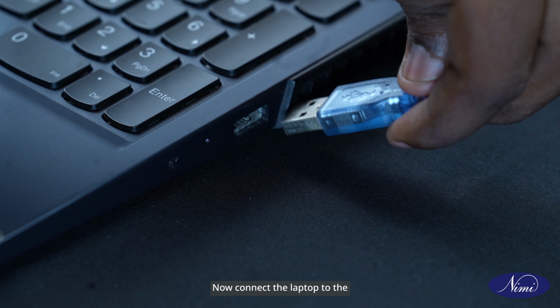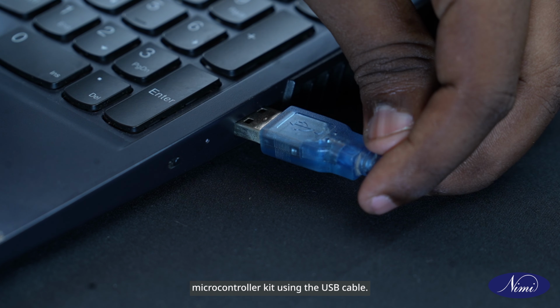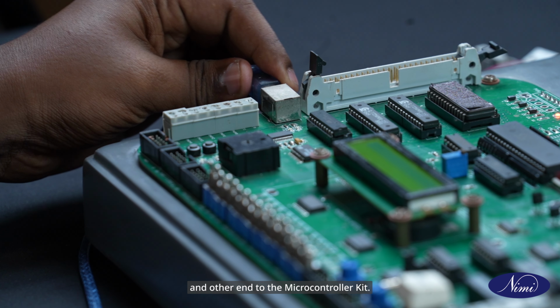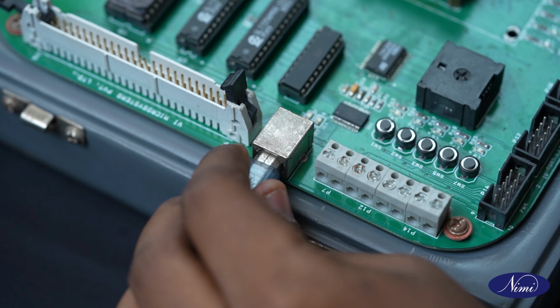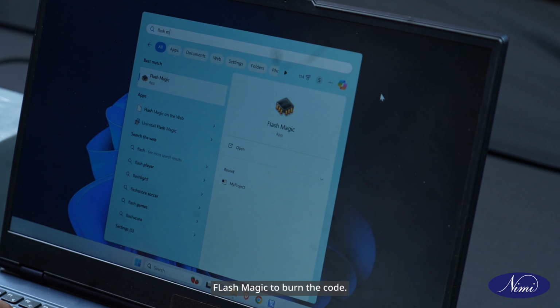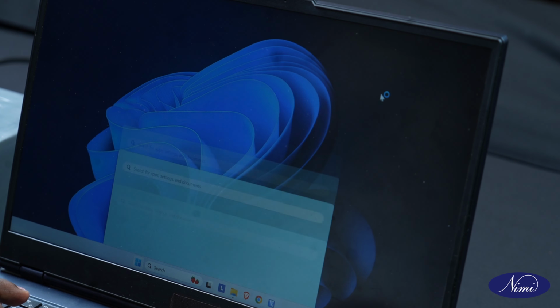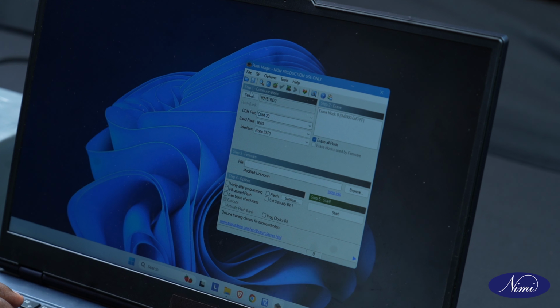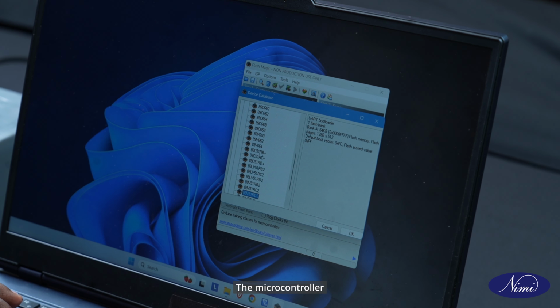Now connect the laptop to the microcontroller kit using the USB cable. Connect one end of the cable to the laptop and the other end to the microcontroller kit. Now click Windows on the keyboard and type FlashMagic to burn the code. Now in step 1, select the microcontroller. The microcontroller specification will vary from kit to kit. Here, we are using